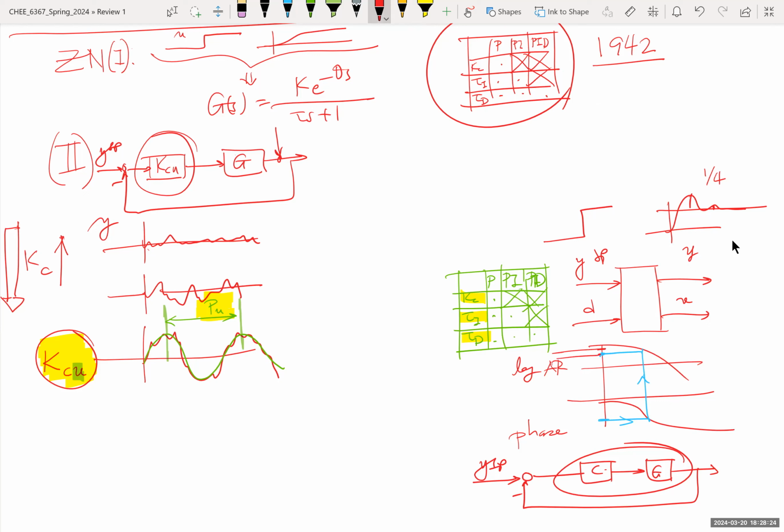Well, when you do this, for the Ziegler and Nichols tuning rule, we have here a margin which is about 50% of the nominal gain. In other words, the gain could double and you would still have stability. And the phase margin, if you go in the reverse, if you go here and you say this is the critical value, so if I go down here and here, am I above minus 180 degrees? This is the phase margin. That is about 60 degrees for Ziegler and Nichols.